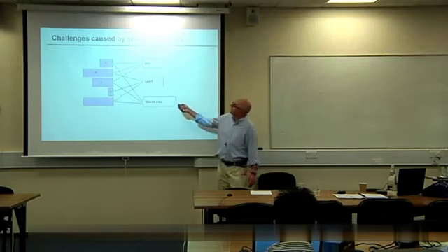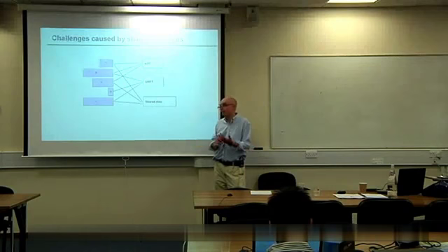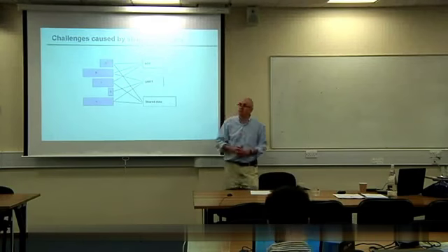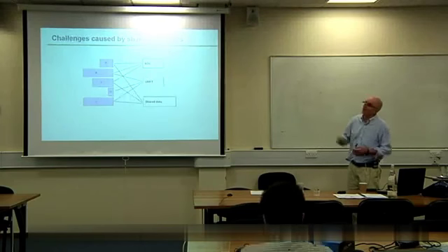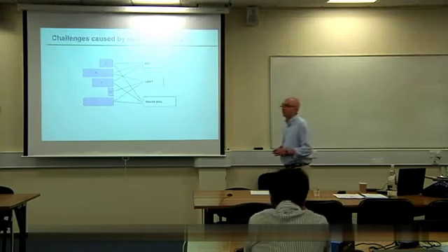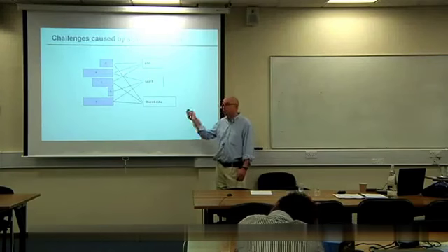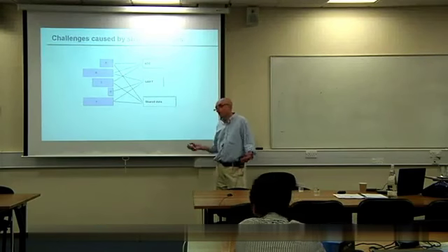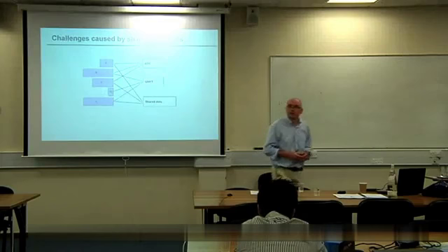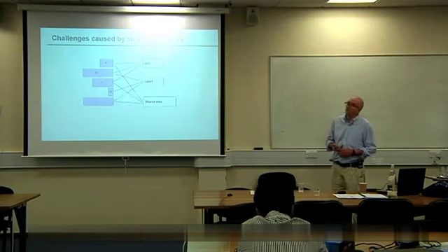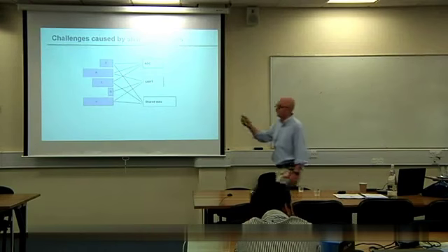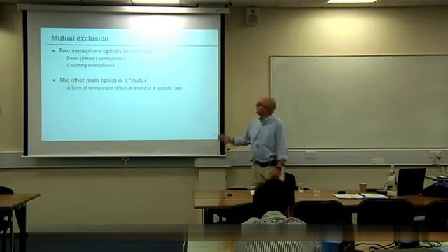The blockage due to the ADC may itself be very short. An ADC conversion is a couple of microseconds. So even if you were blocked, it might be only for a couple of microseconds. But a couple of microseconds might be enough to disrupt the behavior of your system overall in a manner that was difficult for you to handle. Let's take it forward a couple of steps.